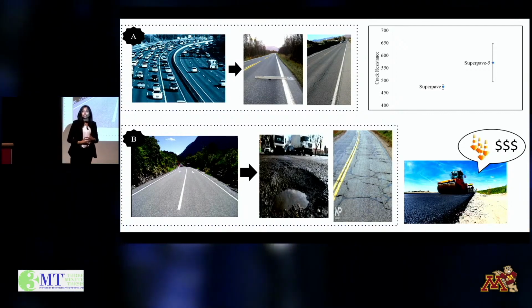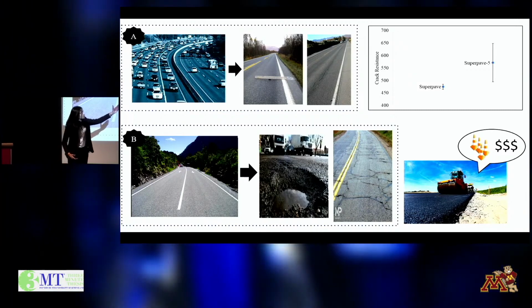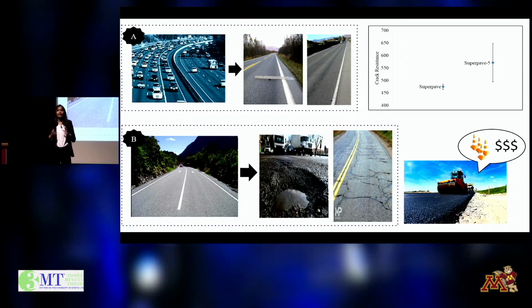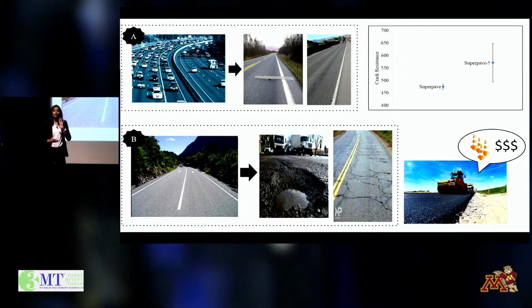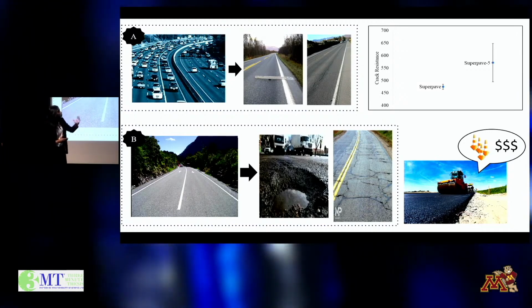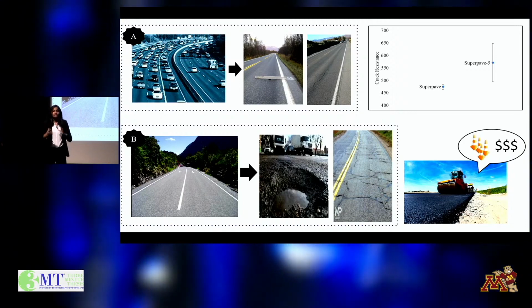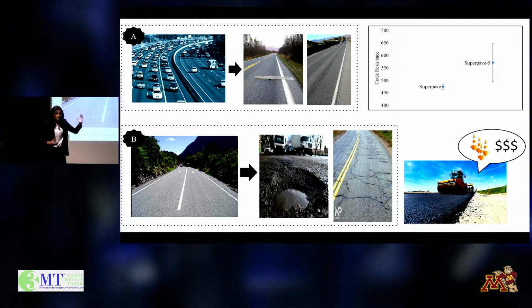For our research, we developed 6 asphalt mixtures: 3 conventional Superpave mixtures, which are currently used in Minnesota with 7 to 8% air content, and 3 Superpave 5 mixes with 5% air content. As you can see, the graph represents the 2 types of mixes and their crack resistance. The strength test showed that Superpave 5 mixes gave higher crack resistance.